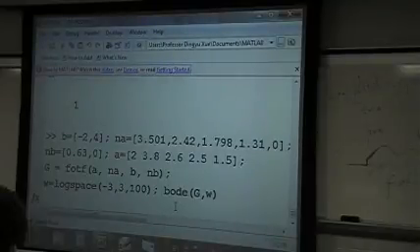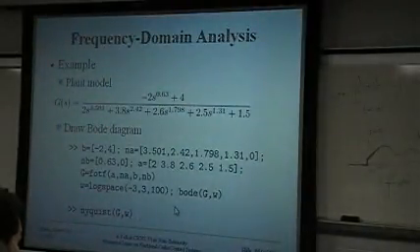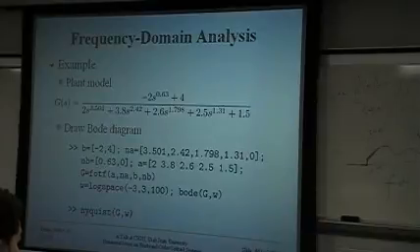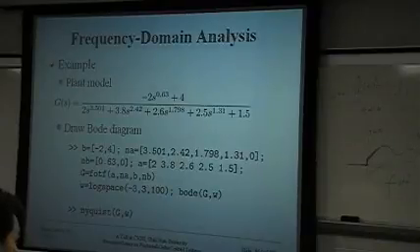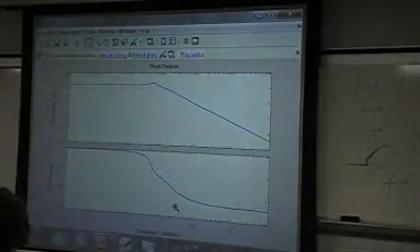So it is a bit slow, because in the Control System Toolbox we use the matrix inverse and some algorithms for integer order systems. However, for fractional order systems we cannot use that algorithm. We have to calculate point by point. So this is the Bode diagram of the system.